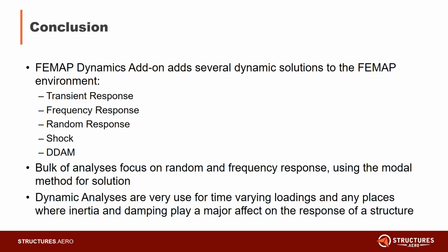Again, also using the modal method for the solution. And again, dynamic analyses are used for a variety of applications and are usually very important, especially if you have a time-varying load and inertia and damping forces might exist in the system. So again, it's a very powerful tool for being able to verify that your structures are going to be able to meet your loads environments and be able to survive whatever loadings you might be applying to them.